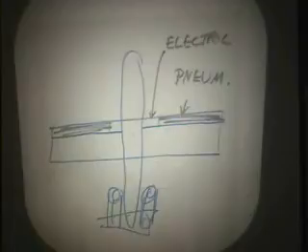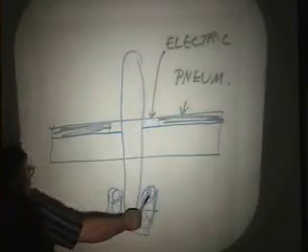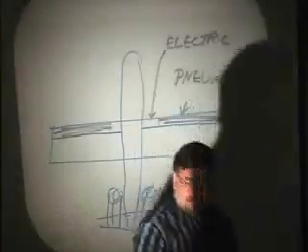So there are some leading edges of wings that have electric, and it's anti-ice. As soon as you think you're going to get into icing conditions, you're going to turn this on prior, because although it would work as a de-icing system, you don't want it to be de-icing. You want to turn it on before the icing hits, so that no ice will stick, so that no ice will end up going into the intake of the engine.